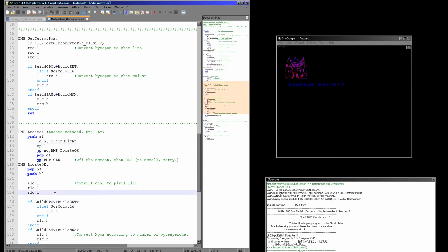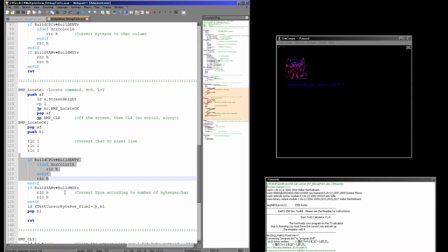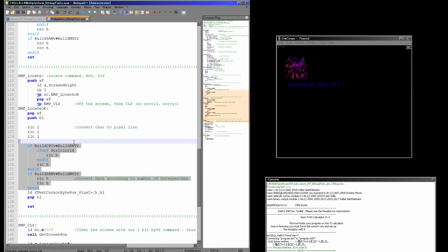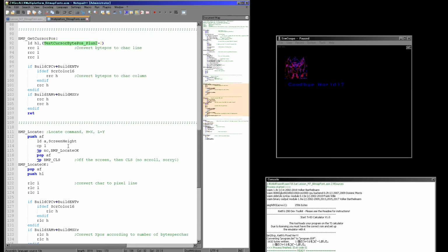But as I say, this is actually enough to get our old examples of reading in input from the user and comparing that input. Remember the sample text adventure kind of thing. We can now run those kind of functions without the firmware font, just with this, so it's enough for now. And again, we just need to do some changes depending on the screen, how many bytes each character uses on the system. So we're doing some bit shifting here to shift the registers into the correct value, and then we store the new location that the characters want to print to with that self-modifying code up here.